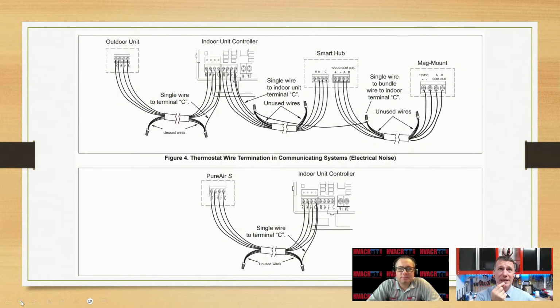But what do you see at that indoor unit? We see 4 wires? Yeah, I do. I got an R, a, I don't see, and a common. So the R and the common, I imagine, would be 24 volts. And the two in the middle, I see a negative and a positive. I can't read what they are, but it's okay. Positive and negative. So there you go. I wonder what those are. Right? So, as elusive as these may seem, they're really not.